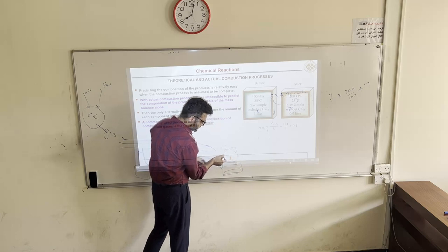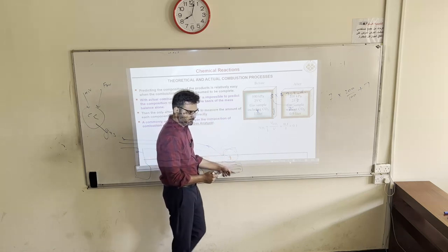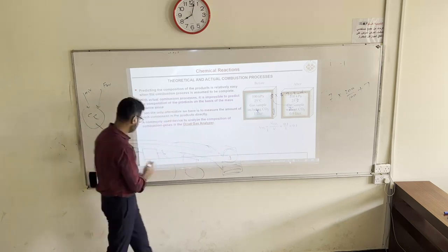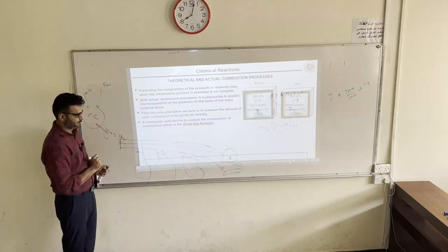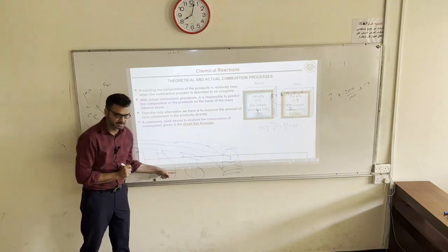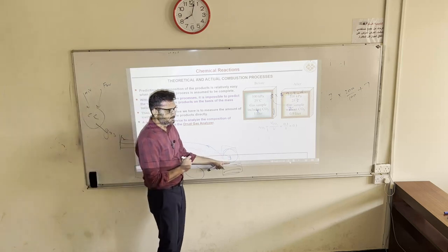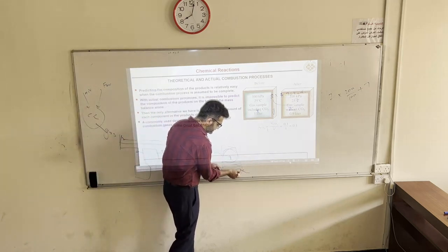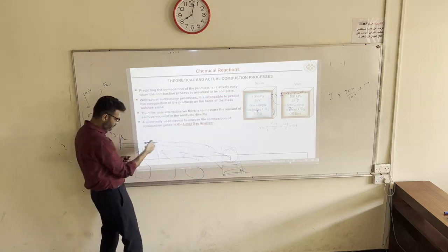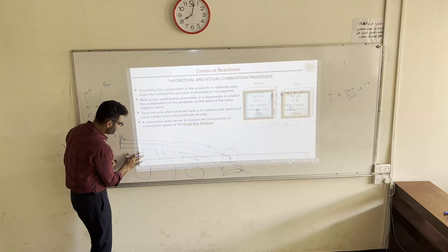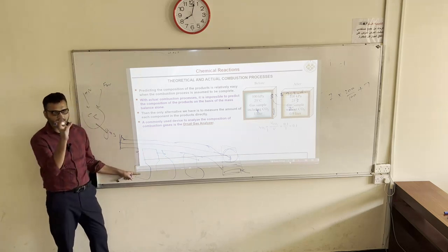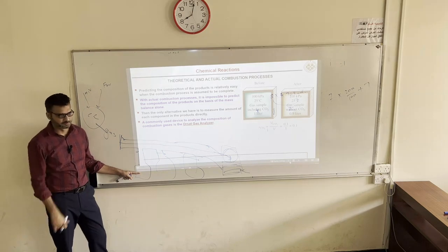It will be present here above the water, and once this gas sample is collected, this is closed. All these are closed, and here we have different chemicals. If I remember, you increase the pressure of this water, it will make this gas flow in this column, and you will, for example, open this one, and here you have a chemical which can absorb CO2, only CO2.